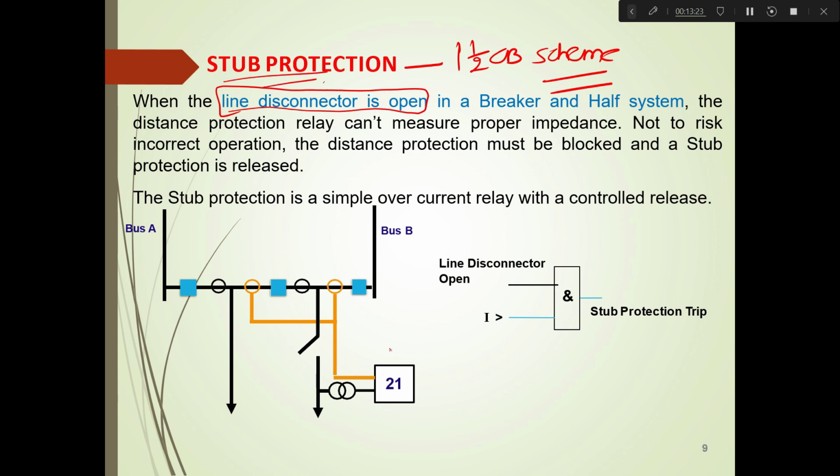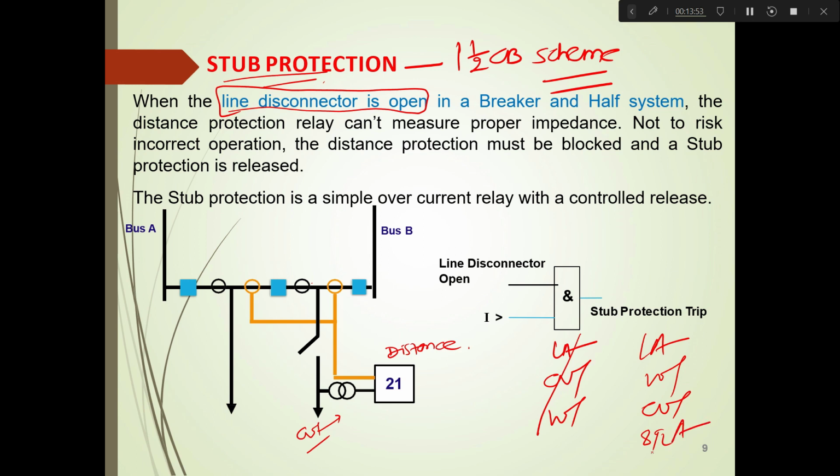So if you see, this is our distance relay, and the two inputs of the distance relay are generally the current, which is connected through the parallel combination of main and tie bay CT, and the voltage which comes from the CVT. Now if you recall the line arrangement, the first element is LA, followed by wave trap, CVT, line isolator, and then the bay equipments.